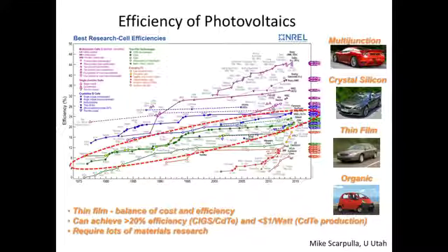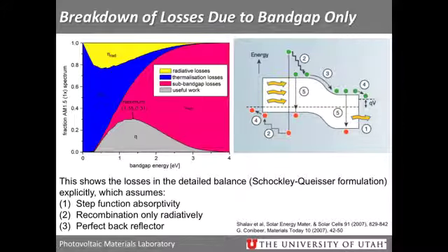Multijunction cells I'll talk about as well. They're more advanced engineering, essentially stacking many PN junctions on top of each other, and that's how you can surpass the theoretical limit for a single junction. As you get into more advanced engineering techniques, and you can stack multiple PN junctions on top of each other, absorbing light at specific different wavelengths, you can surpass this theoretical limit.